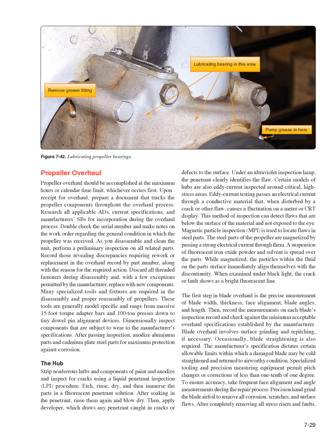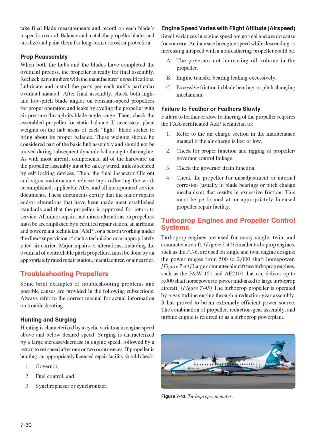Precision hand grind the blade airfoil to remove all corrosion, scratches, and surface flaws. After completely removing all stress risers and faults, take final blade measurements and record on each blade's inspection record. Balance and match the propeller blades and anodize and paint them for long-term corrosion protection.